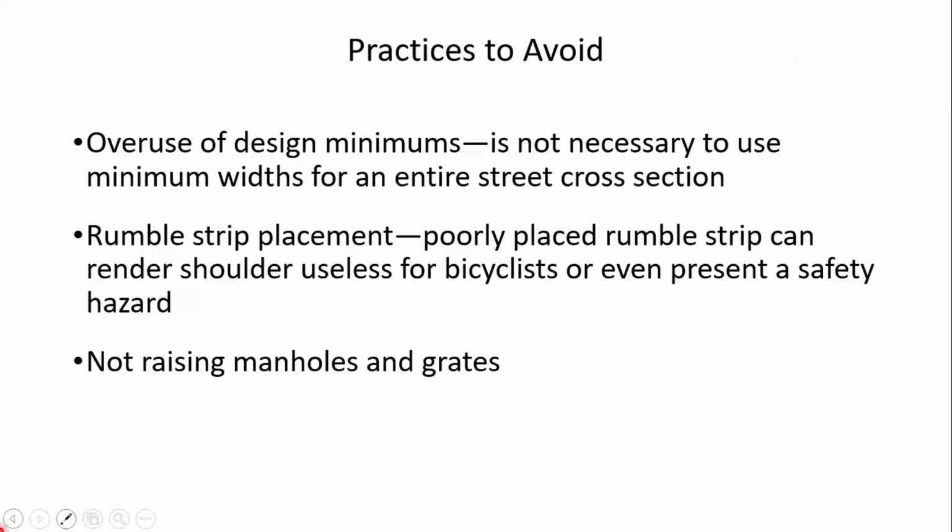Practices to avoid: overuse of design minimums. It's not necessary to use the minimum widths for an entire street cross section. Think about rumble strip placement. We talked about this last week, how poorly placed rumble strips can make a shoulder basically useless for bicyclists or even create a safety issue for them.